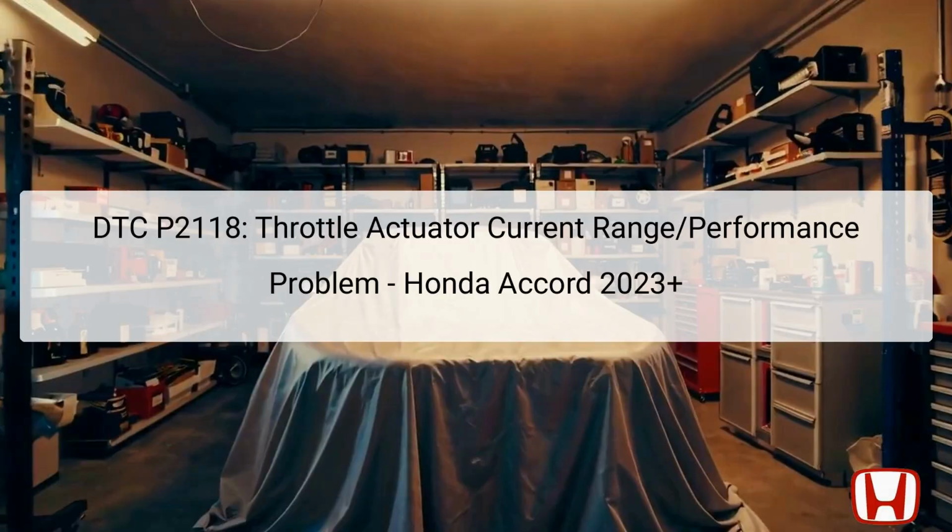This presentation focuses on the DTC P2118, which indicates a throttle actuator current range or performance problem in the Honda Accord model year 2023 and beyond. When the Powertrain Control Module, PCM, detects a malfunction within the throttle actuator for a specified duration, it triggers this diagnostic trouble code. The throttle actuator is integral to managing the engine's air intake, thereby influencing performance and emissions.